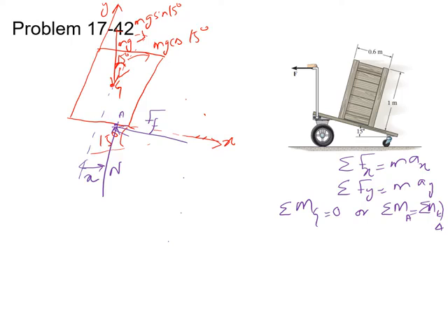Let us start with the sum of the forces in the x direction equal to m a_x. Also, you can write the kinetic diagram for this rigid body. This is the kinetic diagram, and this is the point G. On this point G, this is your ma, and this ma is making an angle of 15 degrees with the inclined surface, as this ma acts horizontally.